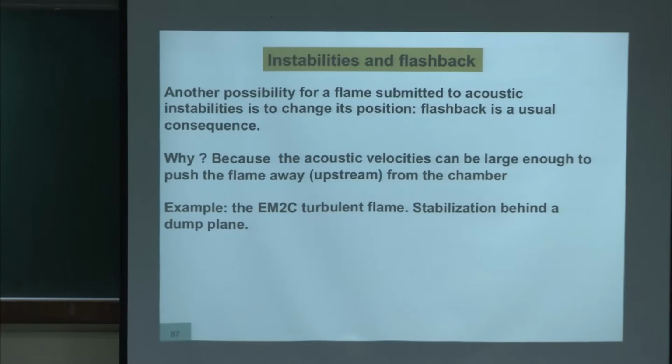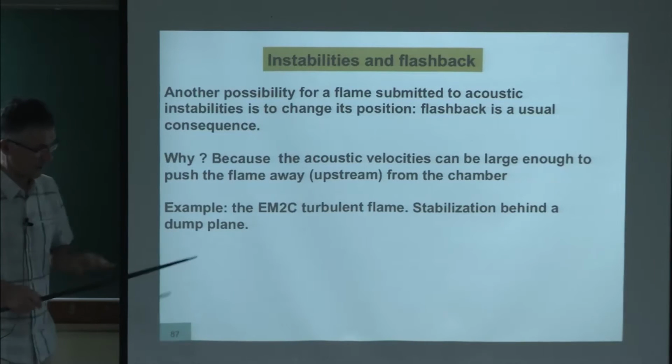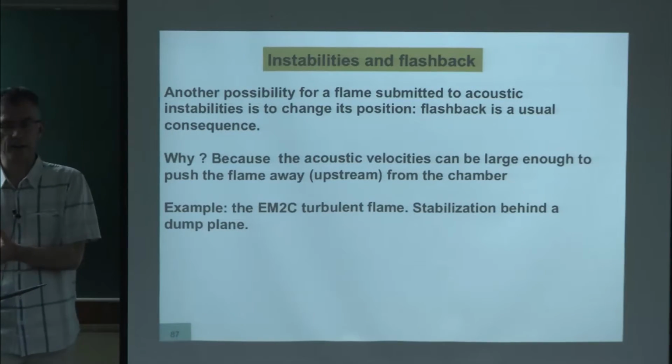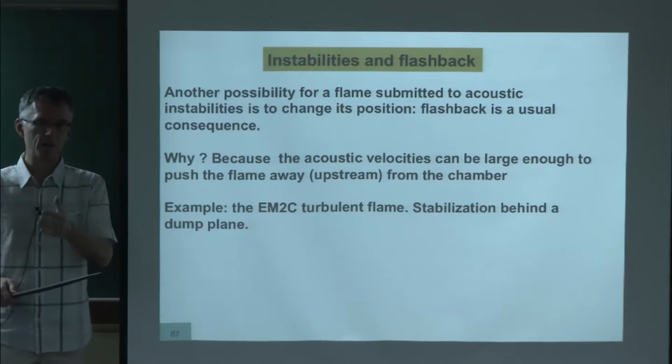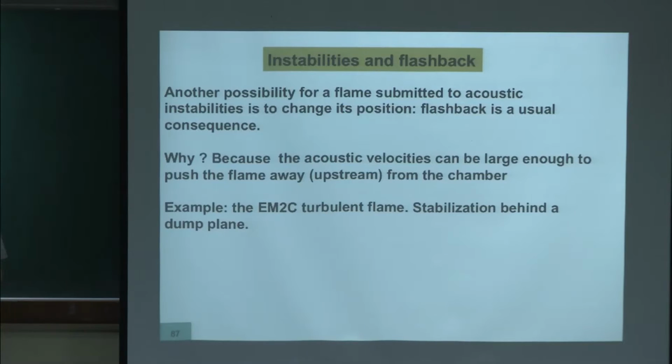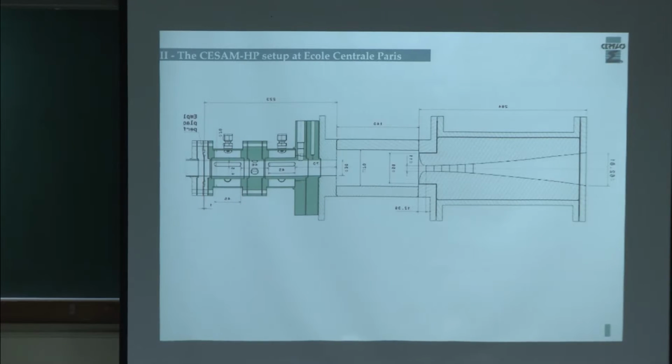Okay, another possibility now is flashback. Flashback is a fascinating phenomenon where the flame, instead of staying where it should be, goes to another place upstream in the chamber. You've seen some examples also in Professor Kushawi's talk yesterday. When this happens, usually the engine is dead after a few seconds. So let me show you one example here.